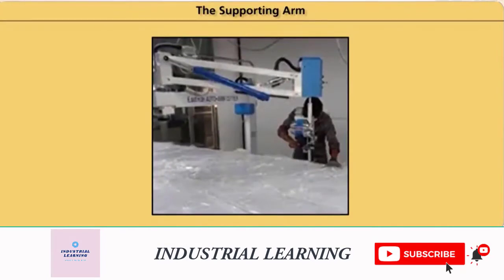The supporting arm. A further advancement to the straight knife machine is the use of a supporting arm that supports the machine from above. Therefore, the heavy base plate can be replaced by a small flat base plate, which reduces distortion of plies, and a narrower blade, therefore enabling cutting along sharper curves. Further, there are lesser chances of tilting of the blade during cutting.